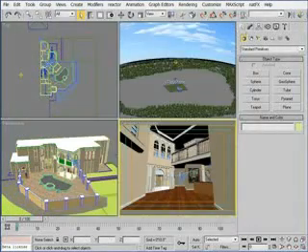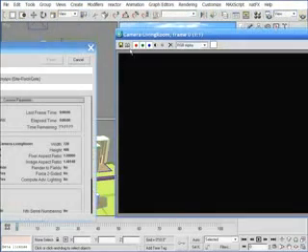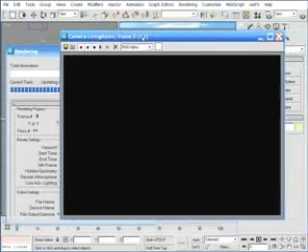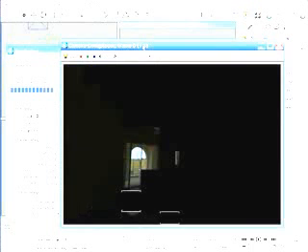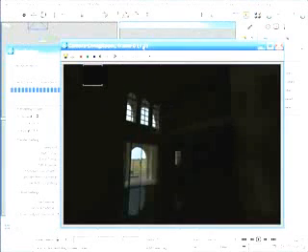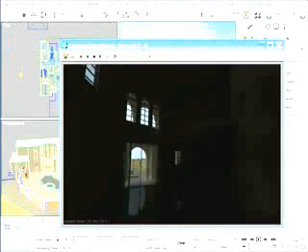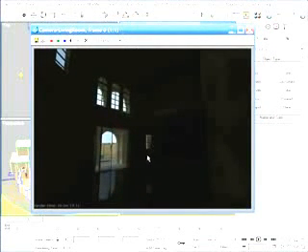first test render. This rendering will take just a few seconds since I have no lights and very low render settings, but whenever I use environment light, which would be for almost any scene, I like to render with just the environment light so that I can see its effect without any other light source, so that I can know for sure when I place that first light what the illumination is in the scene that's caused by the light and how much illumination is being provided by the environment lighting. So this is what I get when I render with just environment lighting.